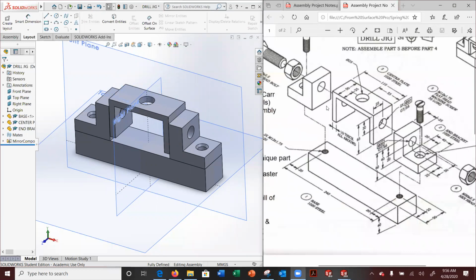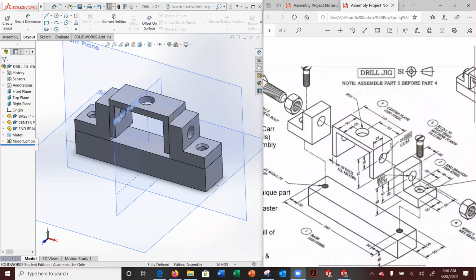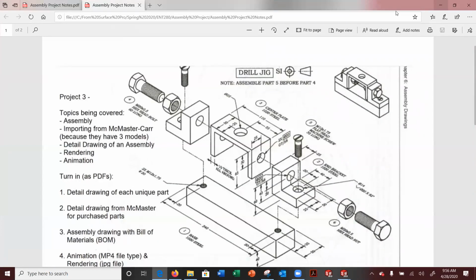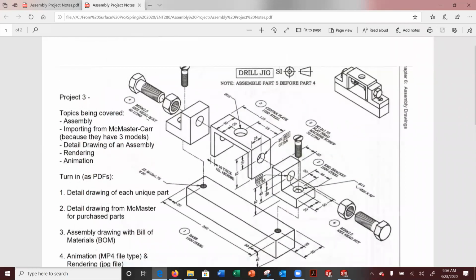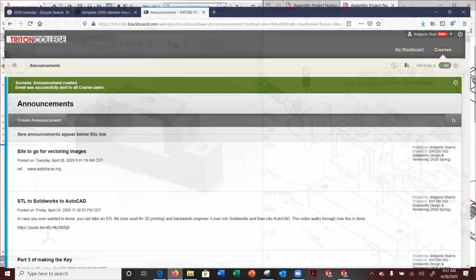So when you're working on purchased items, you're looking at, I have to maximize this. You're looking at two or three types of items in here. We have an M12 flathead machine screw. We have an M20 2.5 hex head nut, and then we also have an M20 hex head bolt, 60 long. They're metric components. So we have to jump online.